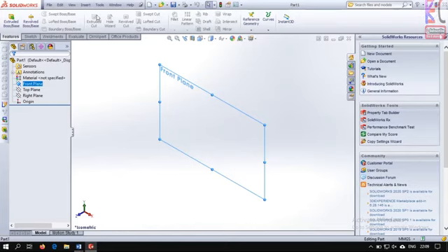Let us understand the things, why this is eliminated and what we need to learn. Now this is extruded boss and revolved boss. What is extrude? Extrude is nothing but the formation of solid parts, which will help us to understand how much is the material. Revolved boss base is used to develop a solid from a 2D diagram, but the thing is that it will be symmetric. In extrude it is not mandatory to be symmetric, but it will develop from a 2D diagram.